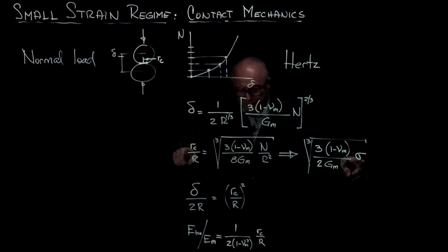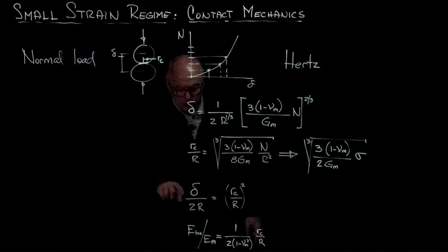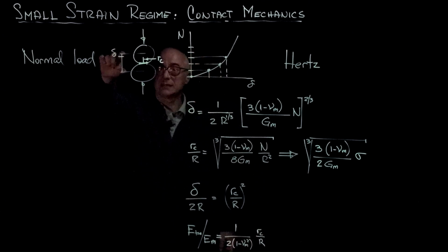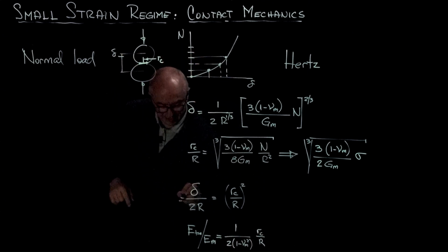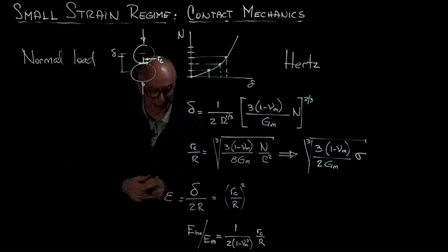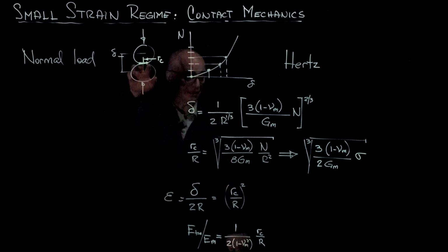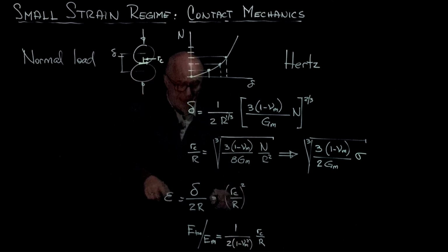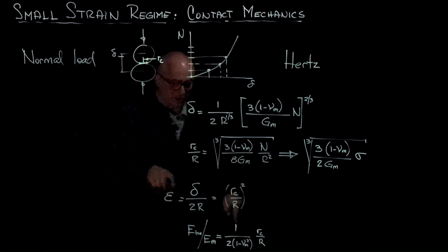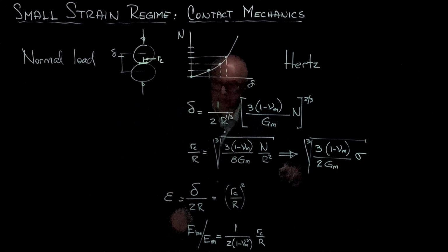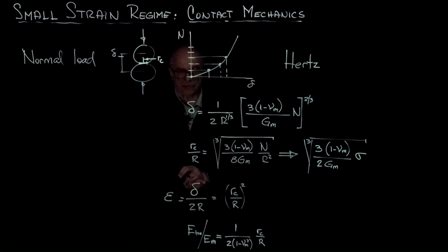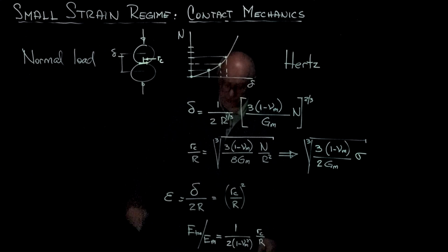But now, please recognize that the shortening divided by the distance between the centers is a measure of macroscale strain, and it is related to the size of the contact. So once again I get a relationship between strain and stress for a Hertzian type behavior in a material where all the deformations are taking place at contacts without fabric change, because we are in the small strain regime.